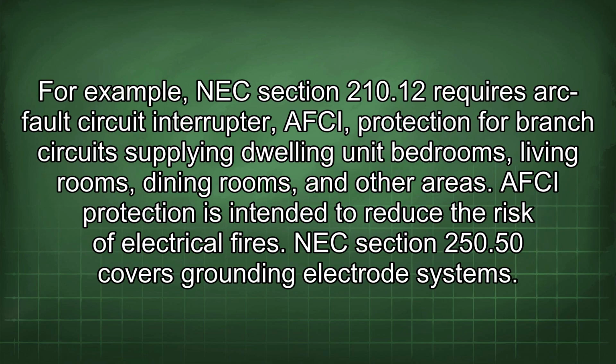For example, NEC Section 210.12 requires arc fault circuit interrupter, AFCI, protection for branch circuits supplying dwelling unit bedrooms, living rooms, dining rooms, and other areas. AFCI protection is intended to reduce the risk of electrical fires.